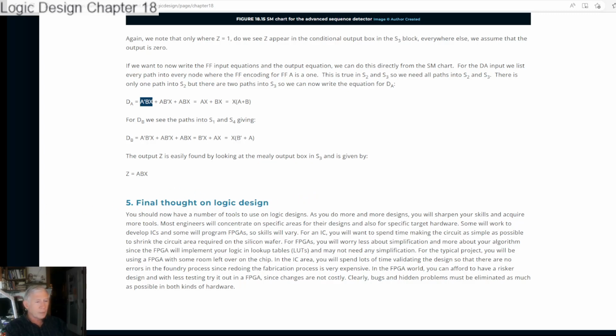So that's often true. All right, well, that pretty much completes what I wanted to cover for this chapter, and hopefully it gives you a good overview. The only additional things to do are just to work more problems, to get more comfortable with more complex sequential designs, and over time, you'll probably spend a little more time looking at adders because they're so important, and especially higher speed adders, because that's what's used in pretty much all modern computing machinery today. Just simply because pure carry ripple adders are way too slow.